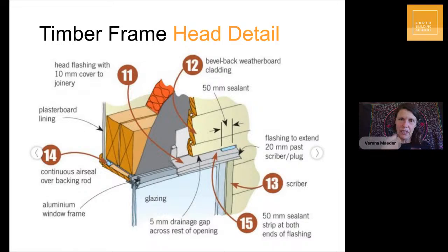But as soon as you have woody materials or light earth materials or anything else in layers, you need to take this quite seriously. So here I'm just showing you, it's quite nicely done. This detail is easy to understand in this more three-dimensional way. They've drawn it. The head flashing at the top of the window here goes behind the timber cladding and then protrudes over the top of the window, so that you imagine if water hits your cladding, the outside of your wall, it can just flow down and then drip off along that flashing.